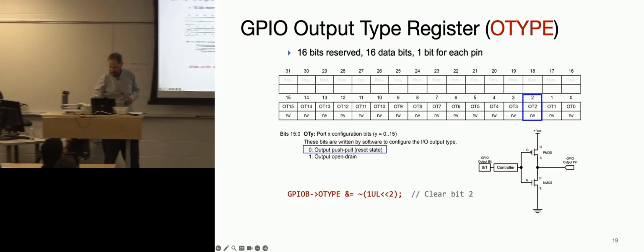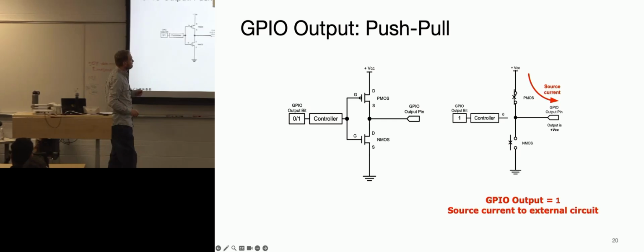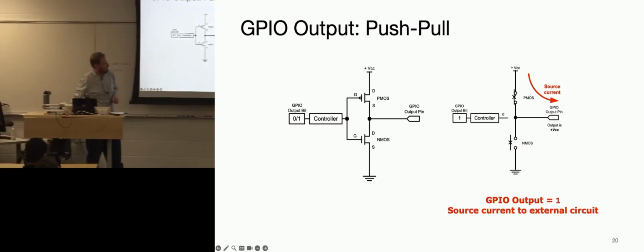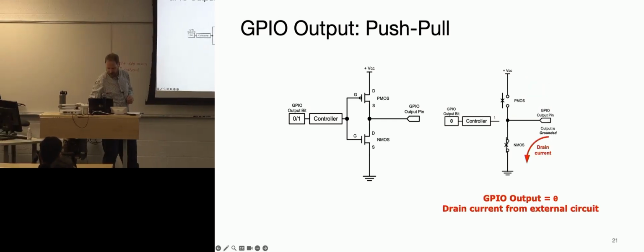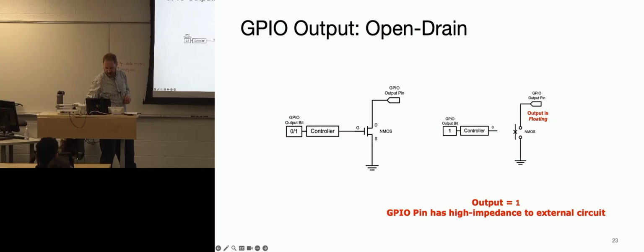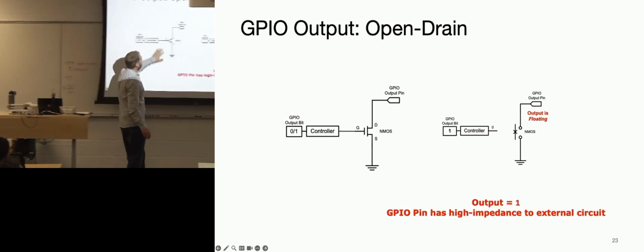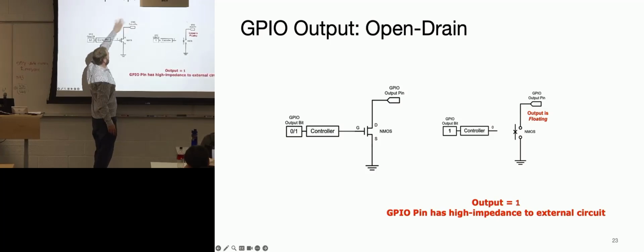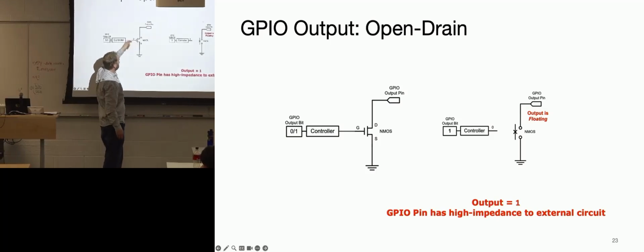The other modality you might want is to have an open drain. Open drain is where there's nothing connected up here. They've disconnected the PMOS, and now this can either hold the pin low or let it float.